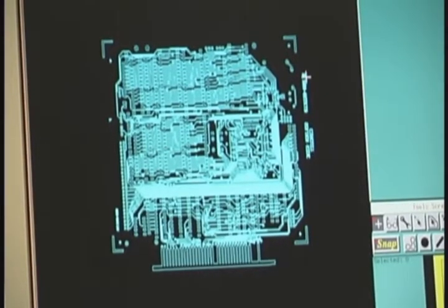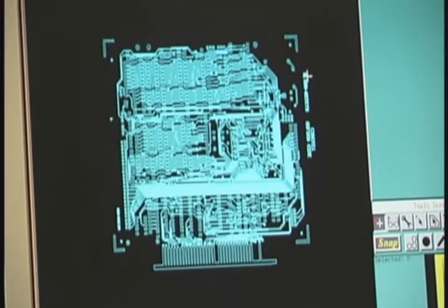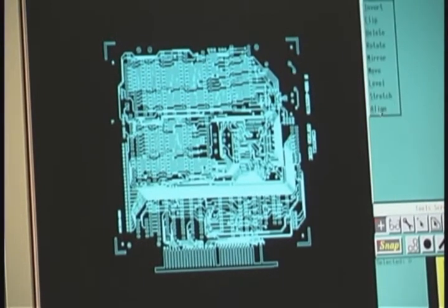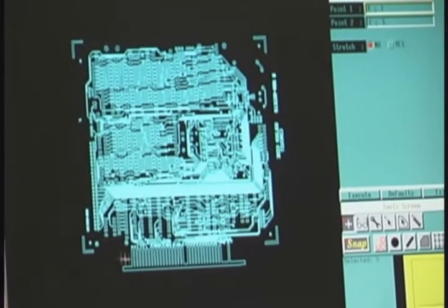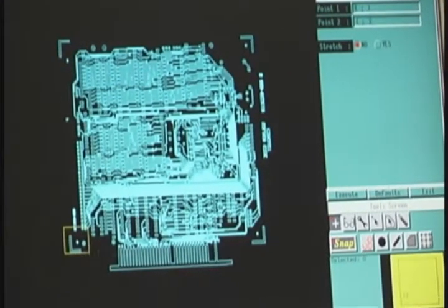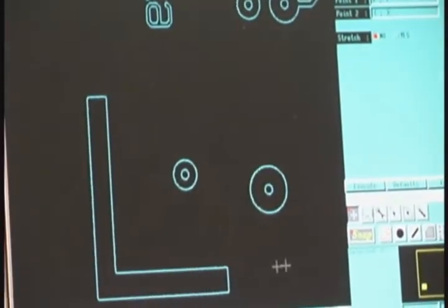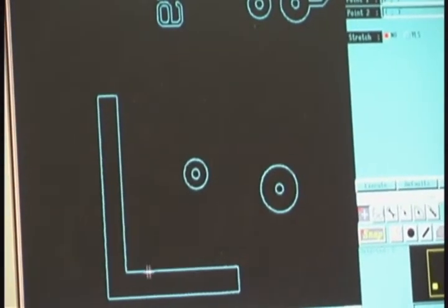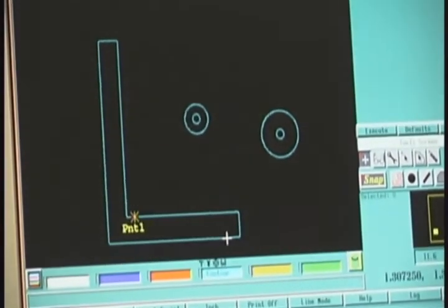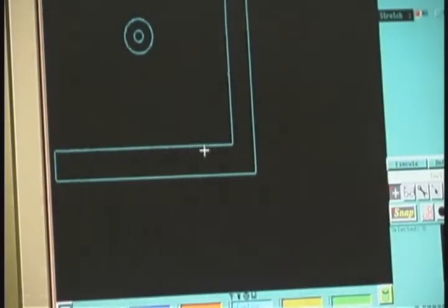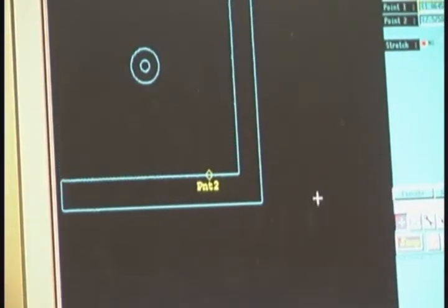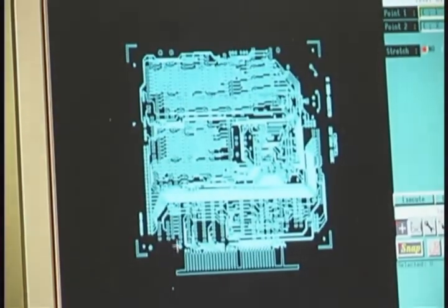When we get the layer that we're going to be working on for editing, the first step that we do is we have to level the artwork. For this case, I'm going to use the crop marks, and I have my snap here set up to the edge of the contour, so it's going to go automatically to the edge of the contour, and I'm going to level it using the crop marks on the board.